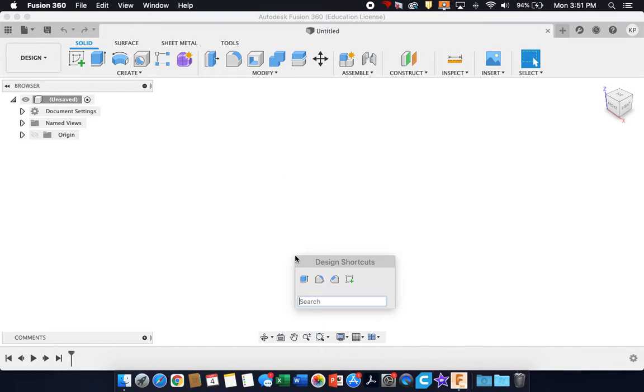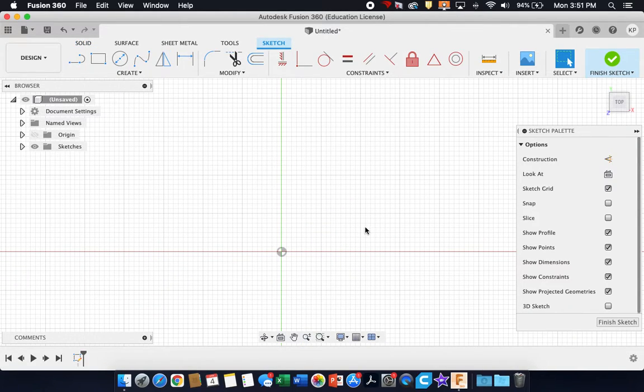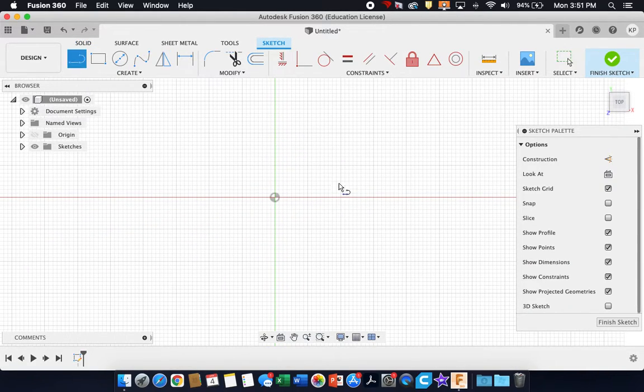So the first thing we're going to do is create our sketch. And I want you to select the bottom plane this time. Use the line tool, and we're going to draw a simple shape, a little more complex than before, but using features you've already used. Sometimes that little check mark gets in the way. Just go around it. Make sure you use your alignment tool and line up with that last one. Click and hold and connect it up.